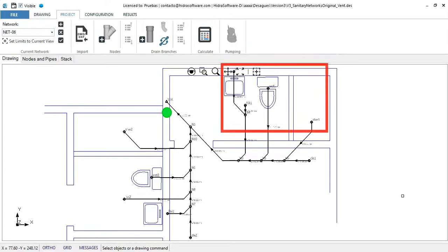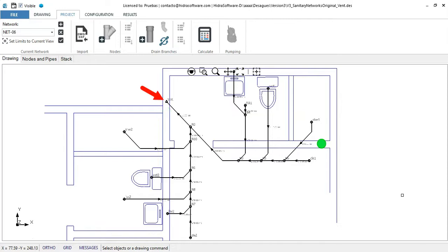Then you will see that here, on the right, the situation becomes complicated by the space in the wall mentioned above, since there is no way to connect the branch vent pipe for these fixtures, which would have this alignment, with the one we have proposed on the left. So the most straightforward solution will be to define, let's say, at this point, a vent stack that, being remote and not connected to the waste stack, we will call independent.